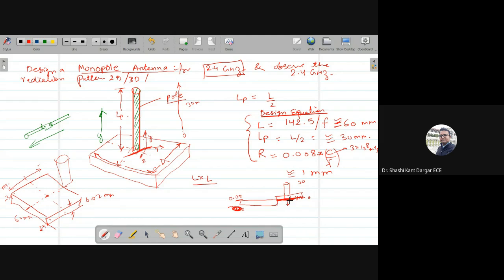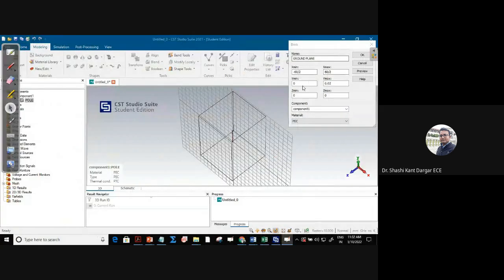So what we are going to do is design it exactly touching each other. So for that we'll take upside. For minus point of view, y direction, we take from 0. So we'll take it as minus of 0.02 to 0. So then we can say it is already overlapped. We want this structure, not this structure. So for that, I write it here as y minimum as minus 0.02. Any problem in understanding this? And y maximum is 0.